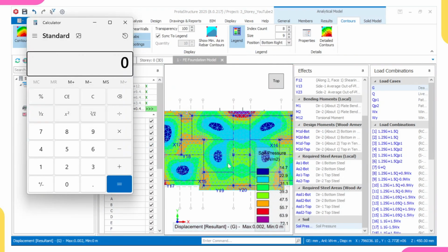If you can remember, the formula for ultimate load in Euro code, remember we are using Euro code, is 1.35 GK, where GK means dead load, plus 1.5 QK, where QK means live load. Yes, that's the formula for Euro code. In this case, what is coming to this structure now, we are assuming is the dead load. So here we are going to do 1.35 times our soil bearing capacity. We use the soil bearing capacity of 70, so we are having 94.5. Please make sure that this value that you are getting here is more than the value here.